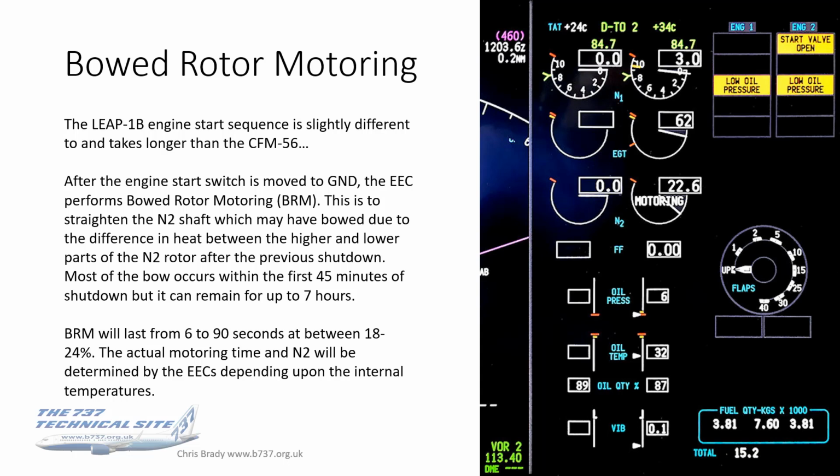The bowed rotor motoring will last anywhere from 6 to 90 seconds, and this happens at between about 18 to 24% N2. The actual time will be determined by the EEC, which does the computations. Basically it's looking at the internal temperatures, and I guess ambient temperatures as well, although ambient temperatures of course have an effect on the internal temperatures. So the EEC sorts all this out, and all you have to do is sit and wait for it to happen.